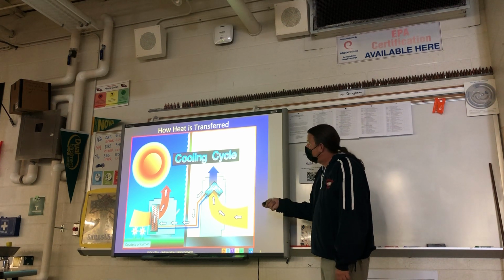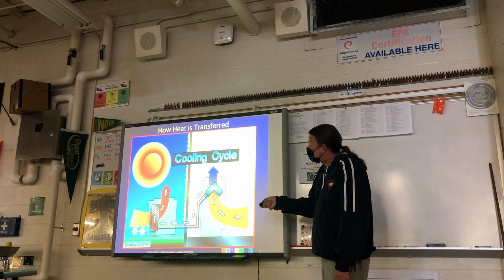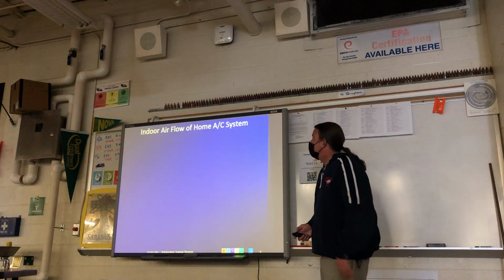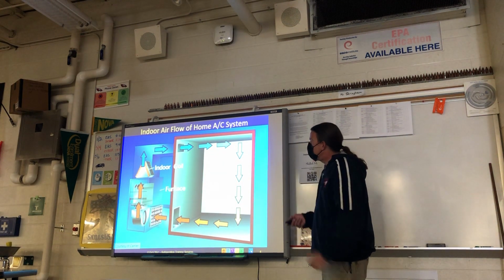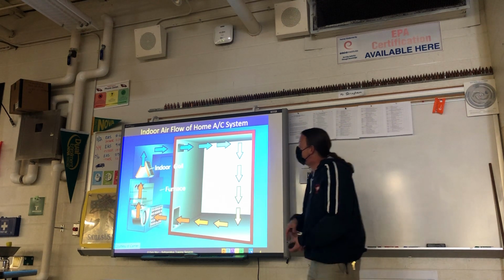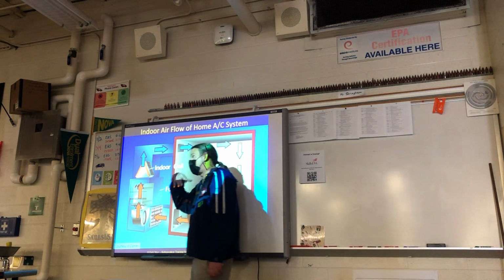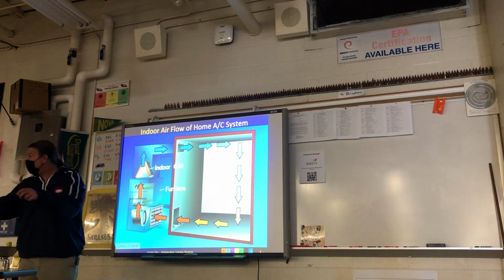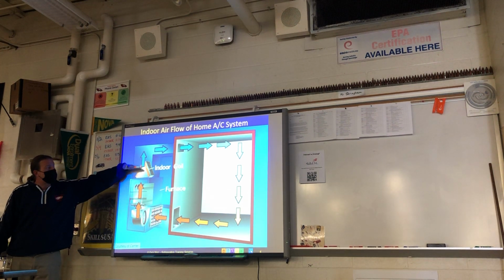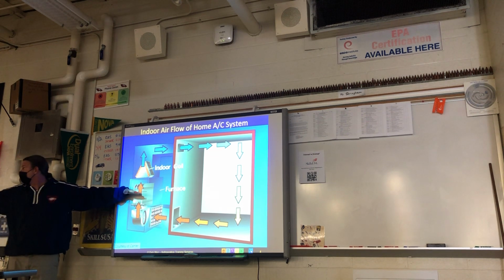All right, so you got the outdoor unit where all the heat's rejected at the condenser, and this probably has a compressor sitting in the middle of it, just like all the other units you've seen out back. The furnace is a little different. The furnace sits in a box. Instead of the air handler, which only moved air over the evaporator coil, this one has the coil sitting on top of a furnace, like we have over here.